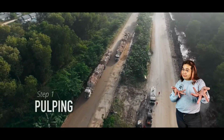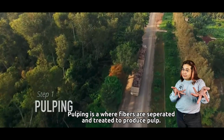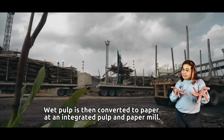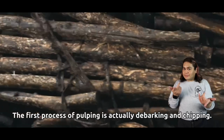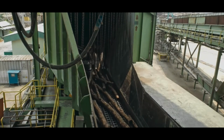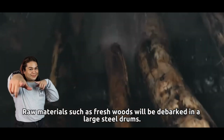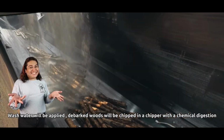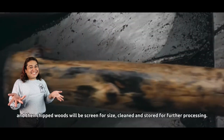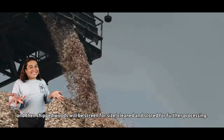What is pulping? Pulping is a process where fibers are separated and treated to produce pulp. The wet pulp is then converted into paper at an integrated pulp and paper mill. The first process of pulping is debarking and chipping. Raw materials such as fresh wood will be debarked in large steel drums. Wash water will be applied, debarked wood will be chipped in a chipper with a chemical digestion, and then chipped wood will be screened for size, cleaned and stored for further processing.